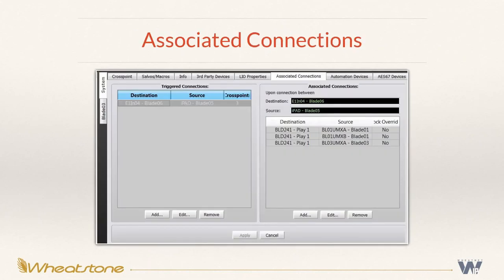This brings up, we talked about the back feeds or confidence monitoring and mix minus, or things we call bus minus, which are clean feeds for home studios or remote codecs. And a majority of our support calls lately have been based on a lot of this. Most of it is a simple matter of setting up the correct bus minus sends. That's a backfeed from one of our faders minus the source on the fader, or a mix minus send or other send where we have to do a lot of custom mixing before it goes back out.